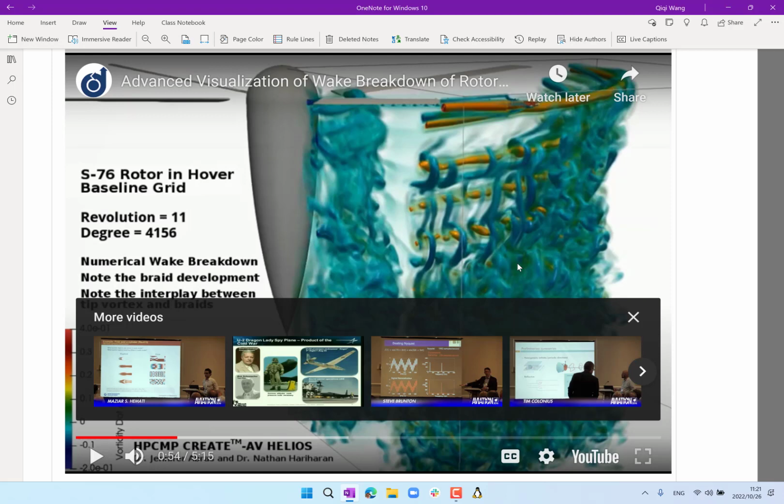Okay, so now as we remember, this vortex is moving inward. As the next blade swipes by, this vortex actually induces a different angle of attack in different sections of the next blade, right? So if this is my next blade and I already have a vortex rotating this way, not at the tip, but a little bit inward of the tip, would it increase or decrease the angle of attack in the small tip section beyond the previous vortex?